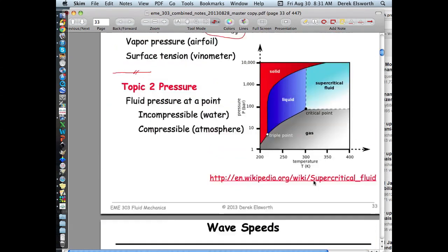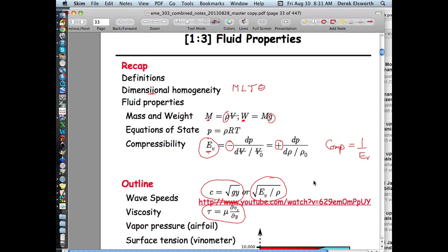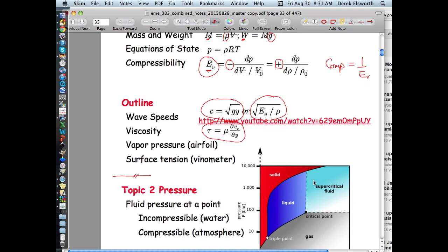Are we going too quickly? I don't hear any comments. Yeah, sorry. We take the radius as the difference of radius of inner piston and the outer. You would take one of the radii and you'd be equally correct in using either of them. The idea is that they're probably very close to each other. So I would take the inner radius and use that. You just need the area of the plug that you're pulling, right? It's an approximation. Other questions?